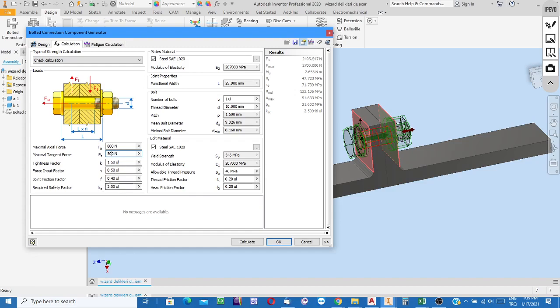What else? Safety factor. Say that I'm not so sure about the manufacturer of the bolt, okay, just obeying all the written things in the standards and satisfied, and so the bolt is a reliable bolt. During the manufacturing there may be some mistakes at this stage, so the strength of the bolt may not be in the order as it is fixed in the standard.